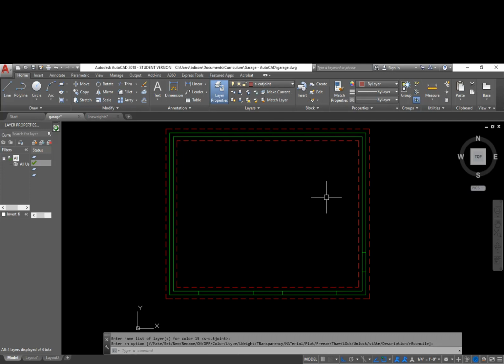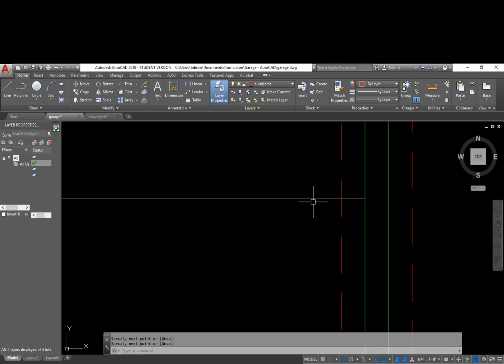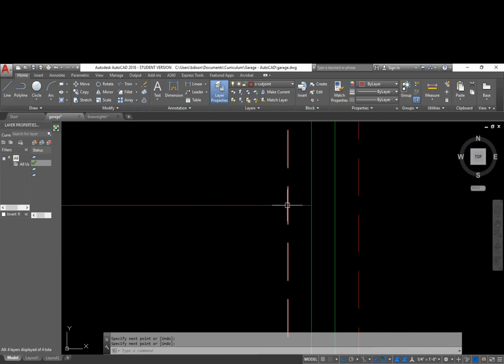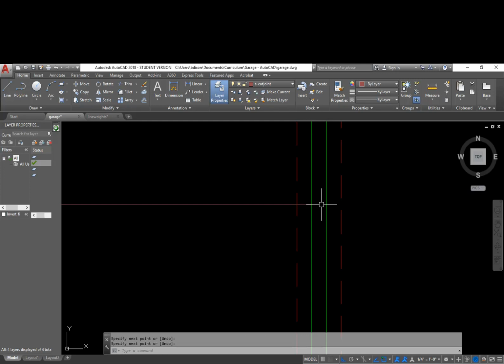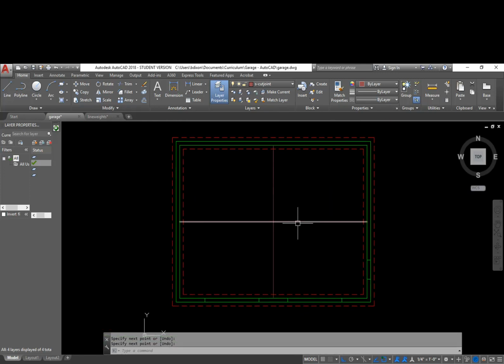So the easiest thing to do for these cut joints in this particular layout is to probably just go from middle of the wall to the middle of the wall. So we're cutting the concrete, and whenever you look at this, it does not stop at the footing because this footing is actually underneath the concrete. So your cut joint is going to go the whole way to the perimeter, this concrete block foundation wall. So right now I have cut joints in place.